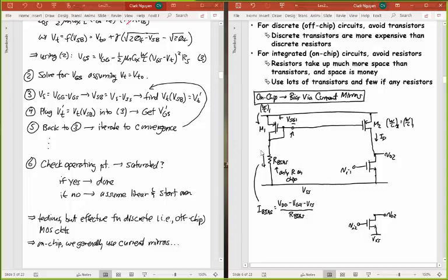That ID, which then runs through this transistor down here, which I'll call M3, that ID has to be equal to I bias. Because the voltage VSG2 for M2 has to be equal to VSG1. So it's basically these transistors.